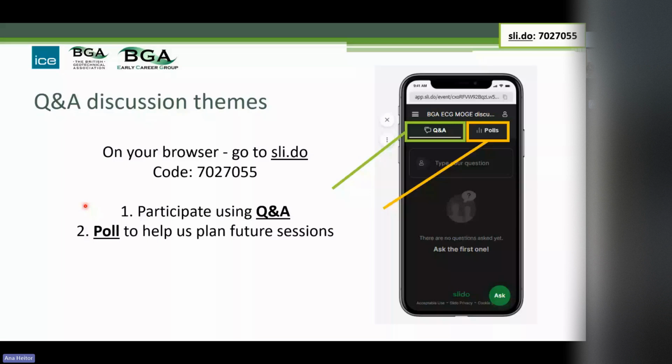Equally, you can take the view that your conceptual model should be driving the design of your instrumentation. So if you're intending to have multiple level piezometers, let's say, that will come from the conceptual model, and then you would say, can I make that a fully grouted multi-level sensor borehole? Which nowadays, once you get more than two level sensors, I absolutely want to go down that route because it's been demonstrated over the last 20 years that fully grouted piezometer installations, designed and installed by experienced contractors, give high quality results.